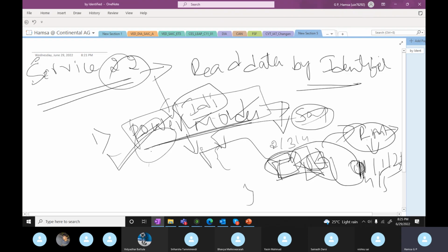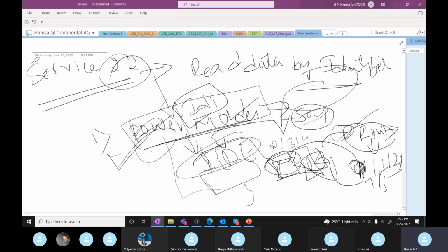So at that time, if you do not have the identifier, what you have to do is open your white box, nothing but the IDE where you write the code, and understand where this particular variable is stored in memory and how big it is, read this memory, and again create the situation or update this variable for the other power modes and read this memory.